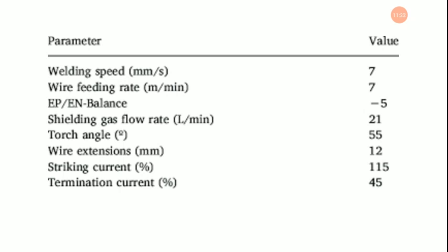Now the percentage of contribution, that is non-significant process parameters for penetration. As penetration is a higher-the-better type quality characteristic, it can be seen that the optimal GTAW process parameters for maximum penetration are IP 205 ampere, IB 103 ampere, speed 200 millimeter per minute, frequency 6 Hz.